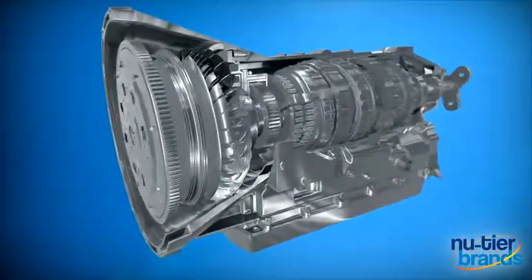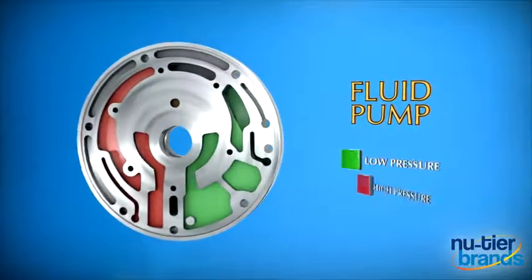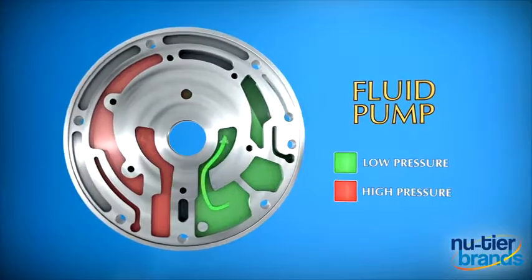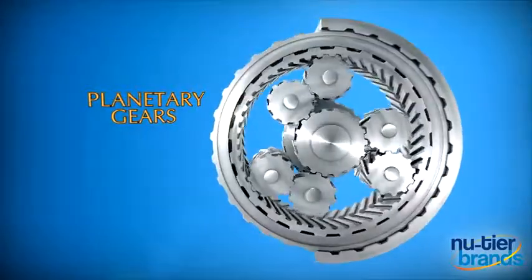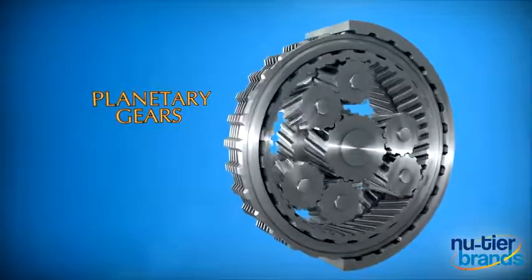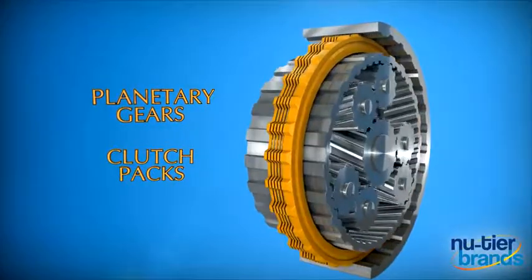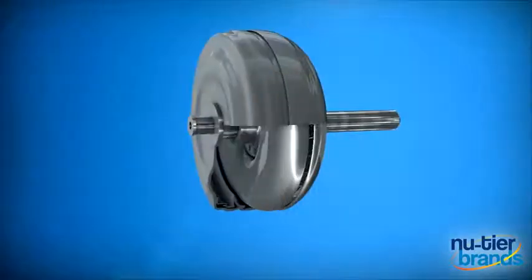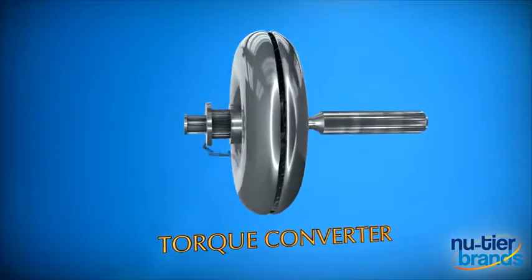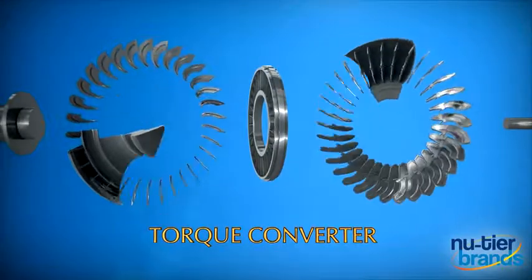There are several main components that make up a step-type transmission. The pump supplies pressurized transmission fluid for many uses throughout the unit. Planetary gear sets provide the chosen gear ratios for the vehicle. Clutches, or clutch packs, engage and disengage the gear sets. The torque converter connects the transmission to the engine and multiplies the torque during initial acceleration.